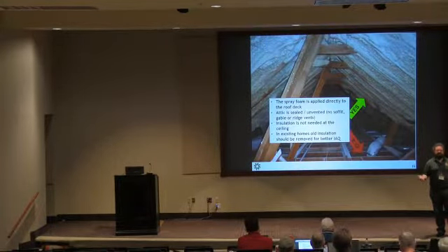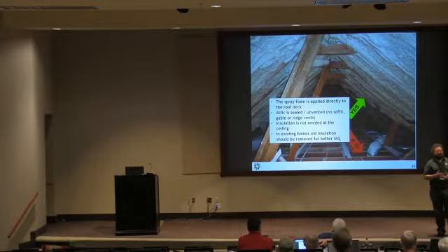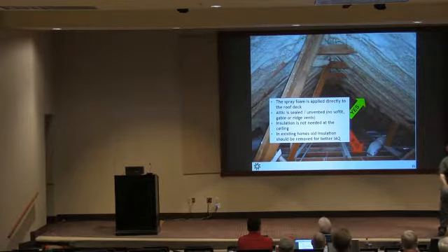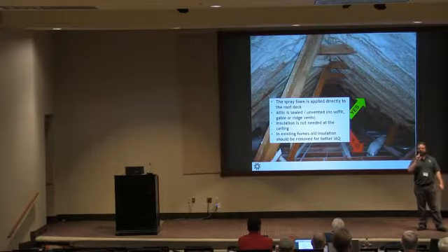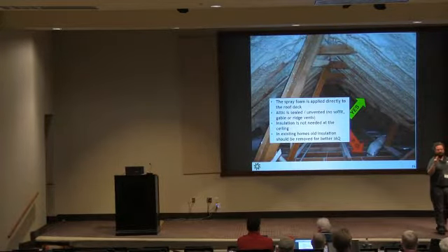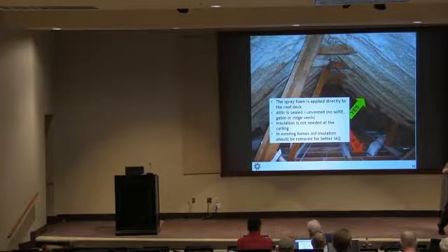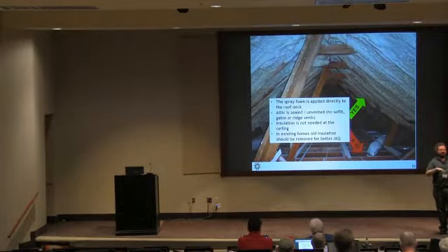But the flip side of it is I would still take out the old, and we often see in that world what is called a flash and batt, where they take out the old insulation, put down like a 1/2 inch or 1 inch of foam, just basically to air seal and provide a little bit of R value, and then they'll dump a more affordable product on top of that. That would be a really good way to air seal the ceiling plane in an existing home. But I would only consider that if my mechanical systems were entirely in the basement.